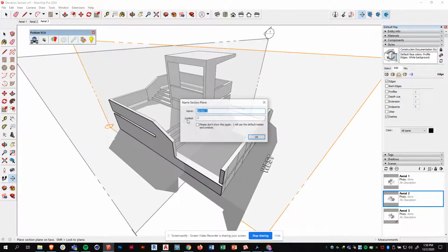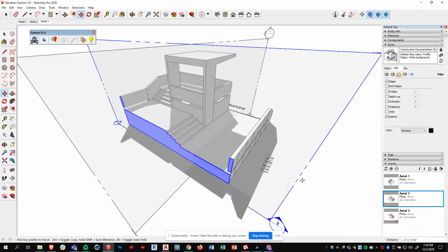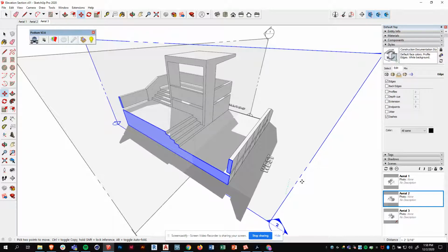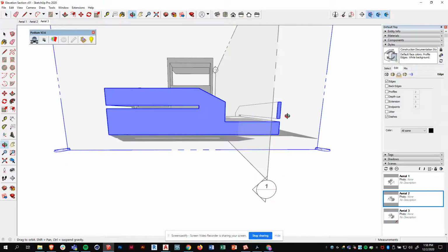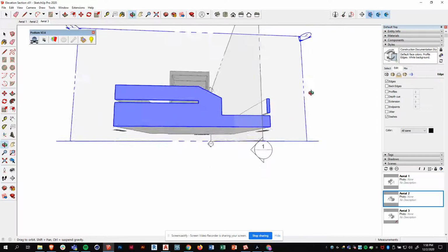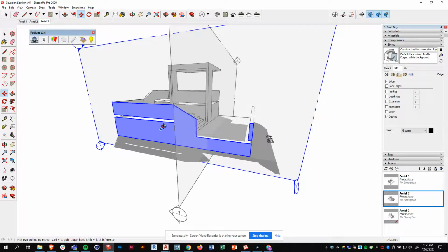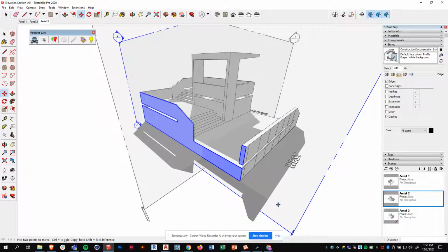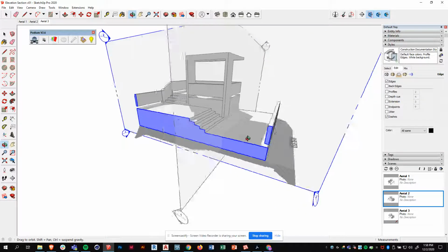I'm going to put one right here. Yeah, we can call it that, that's fine, SketchUp. And I'm going to move it in here. Now, you never would want to take a section cut like this, through a wall, because that isn't very descriptive. It's really not showing the space. What that tells me is that there's a solid chunk of something going the whole width from my screen into the drawing. But that's not the case, because that wall is really thin, and it's more like this. There we go.